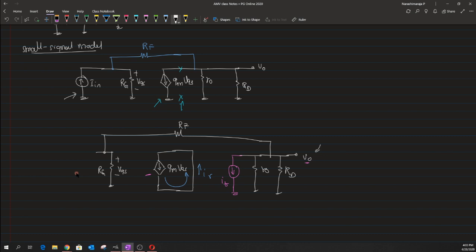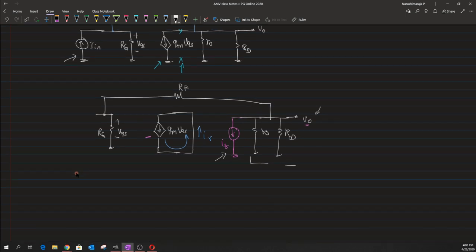Okay. So now let us try to evaluate this impedance or this output node potential V naught here. Now basically since we are pumping in a current and we have a bunch of resistances here, one could easily calculate this output V naught, right. But one has to be careful in evaluating this. Okay. Now one could see that r naught and Rd are not only connected between this node V naught and ground, but there is also one more branch of resistance that gets connected.